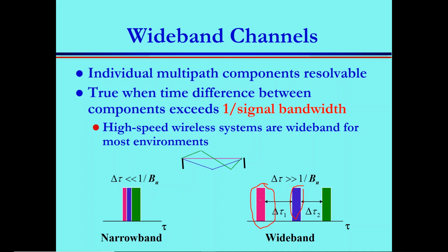So at each tap here, you have the previous distribution, which is Rayleigh, Nakagami, whatever, because you have multipath components, a large number of random received signals that are added to each other constructively or destructively. This nature of addition of a large number of random variables, which are assumed to be Gaussian, gives a Rayleigh envelope distribution, or Nakagami, whatever, based on the environment.